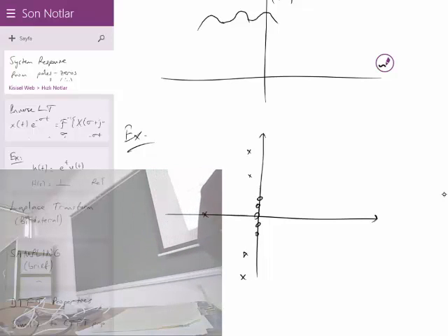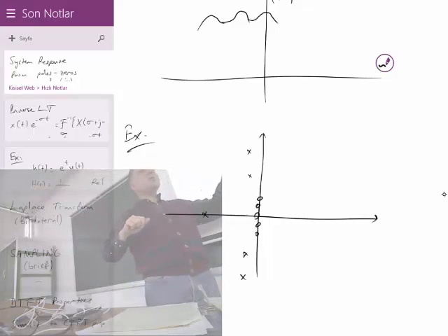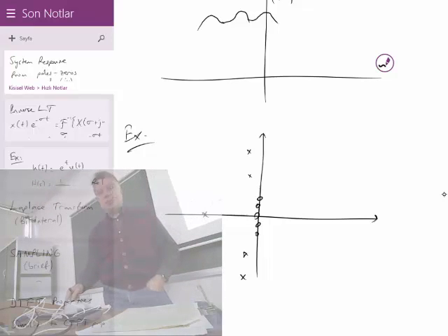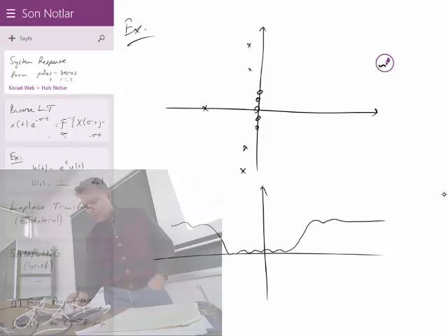And as we come here, it will make a peak and another peak, and at infinity it will stay in a constant value because the number of poles and zeros are the same. They are both 5. So I expect that the situation is something like this. Some sort of a high pass filter. But I'm not quite sure about the overshoots, the fine tunings and all these things. Okay? It's just the shape that I'm describing.